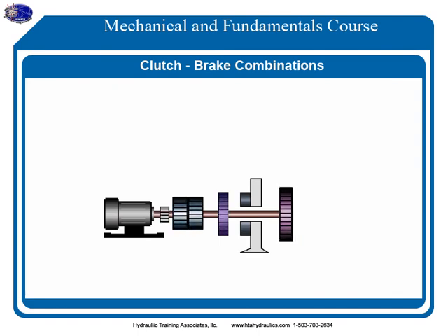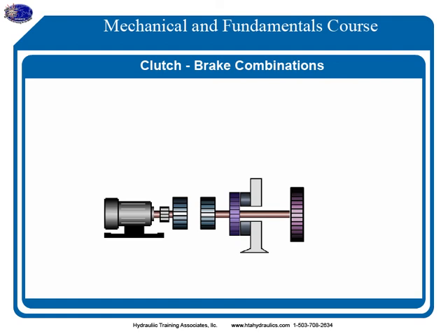When the clutch is disengaged, the motor continues to turn at a full rated speed and the flywheel continues to coast. As the brake is engaged, the friction between the two discs resists the torque from the output, which is connected to the flywheel. As the discs engage, they may have to slip a great deal before the flywheel comes to a full stop. Finally, they will lock into a positive mechanical stop.